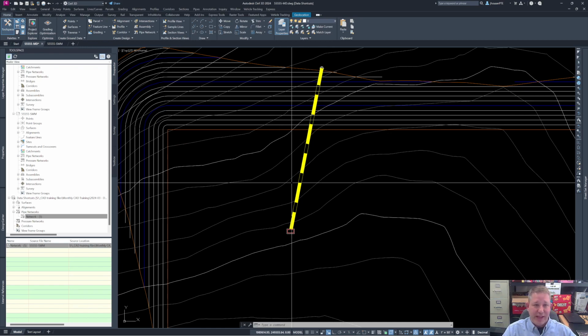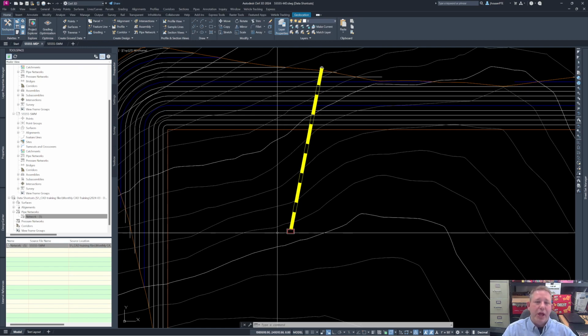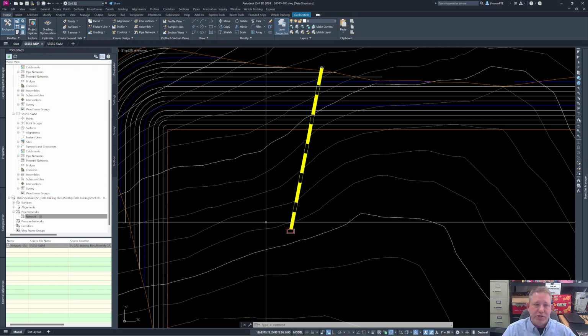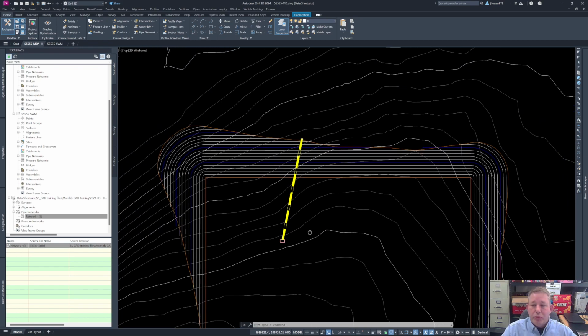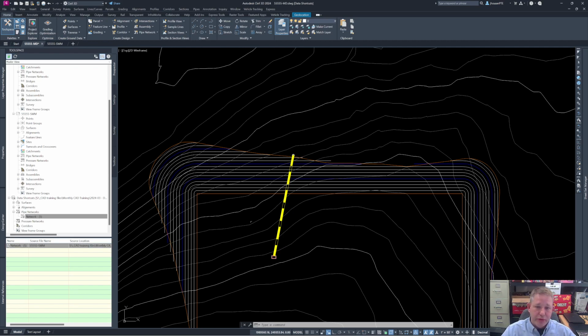I'd rather do it in the MD or somewhere because you would still be XREFing this drawing into your sheets. So one nice thing about it is that anybody in the environmental department can label all their things a certain way if they need different information, while the design department can label it just with tags. Survey can do the same thing with existing.